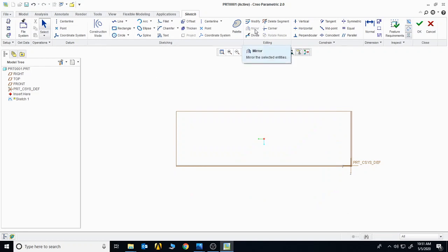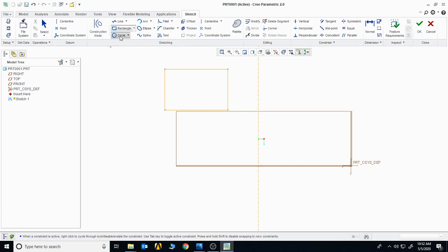Now let's just go into the mirror command, which is most important of all. The mirror command is used to mirror the selected entities. That means that if you have already drawn certain entities and you want to draw that again, you don't need to draw that again. You simply need to mirror that against a center line. For mirror, a center line is a must. If you haven't drawn a center line, your objects will not be mirrored. For example, I select a single center line and draw it here. Okay. Now let's suppose I have made a rectangle here and a circle here.